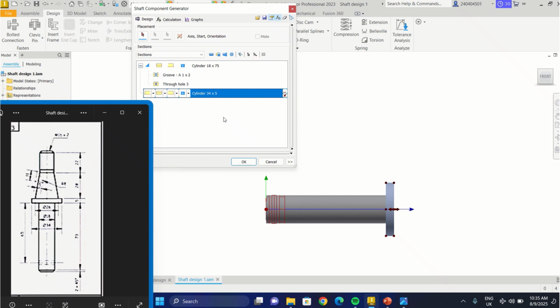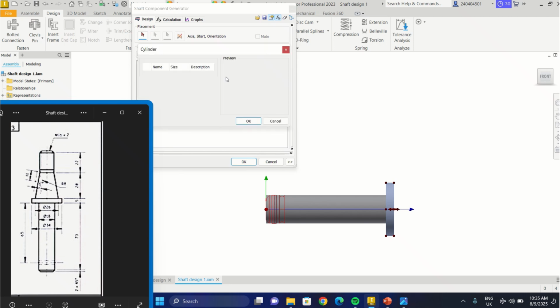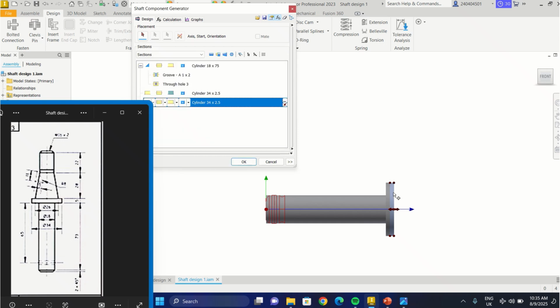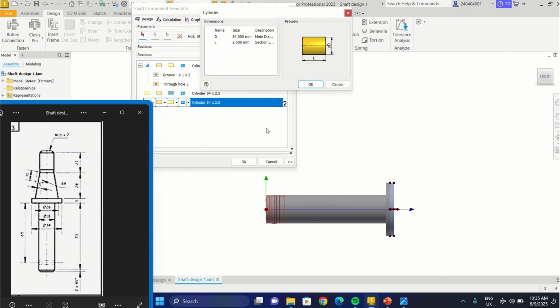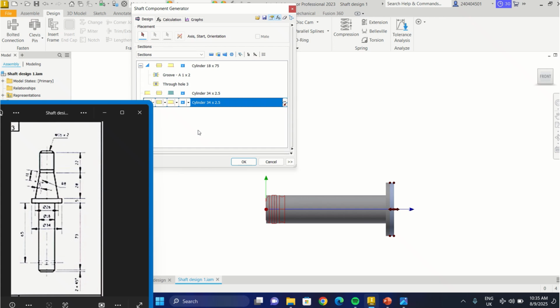The next thing is this conical part. Now, if you look, this is still a split section of the part. So that is a step, so that's a step shaft. If I click on this, it's going to add in another step here. So all I need to do again is specify the diameter, the radius, and the length. What I want is not the split section, what I want is a cone. So click on cone, which is this one. Let me delete this and go back.